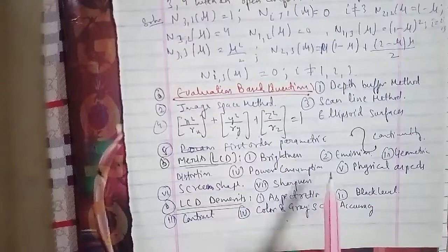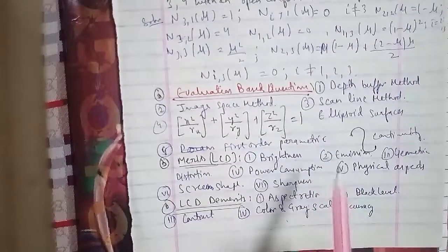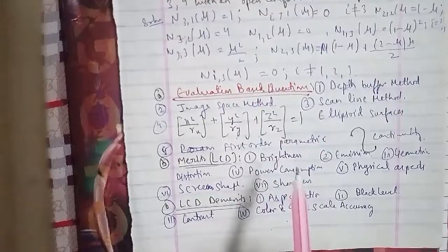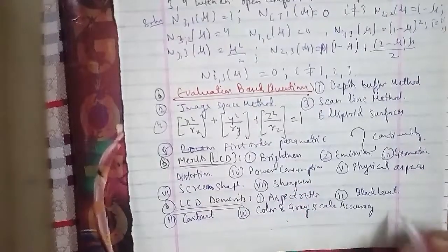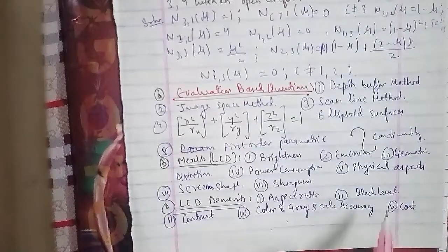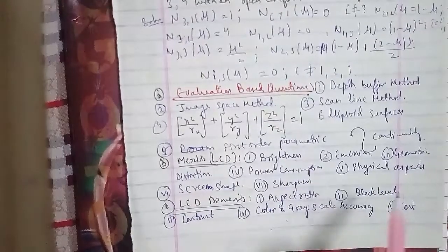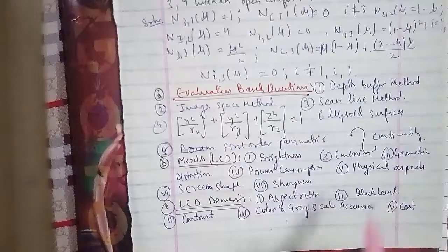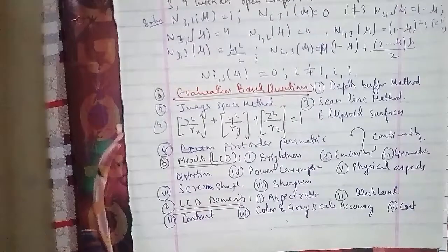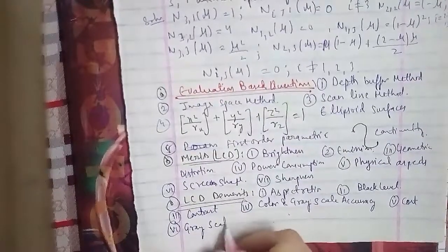Slow response times and scan rate conversion result in severe motion artifacts and image degradation for moving or rapidly changing images. The eighth is resolution. It works best at a native resolution, and the native resolution cannot be changed. All other resolutions require adjusting procedures, which can cause considerable deterioration of the image. The ninth is viewing angle.